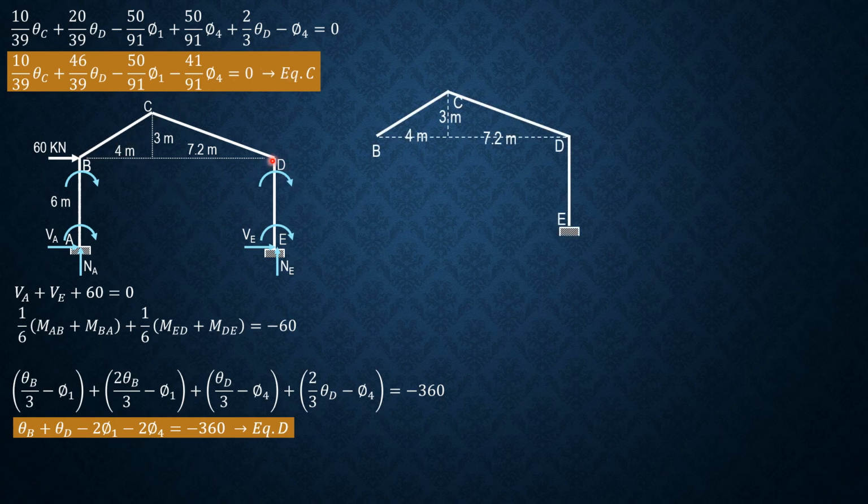We consider BCDE, and let's have the shear reactions at B. Let's find a point of intersection between BC and DE so that we sum up moments there, so that only the shear forces will have moments about O. So remember, this is 7.2, that's 3, 4, so 5 meters. Let's call that Y, call this Z. Then by similar triangles, these are the reactions and shears assumed.